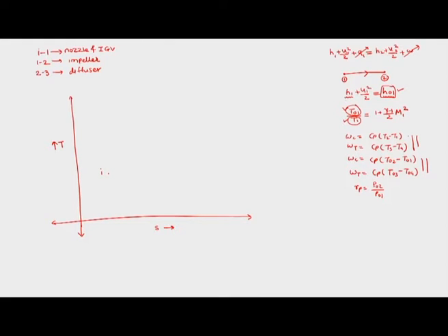Okay. So we were here at I. From I to 1 the flow goes through the nozzle and is accelerating. Since the flow is accelerating, its temperature will decrease, but there would be losses, so entropy would also increase. So we come from I to 1 in this way.